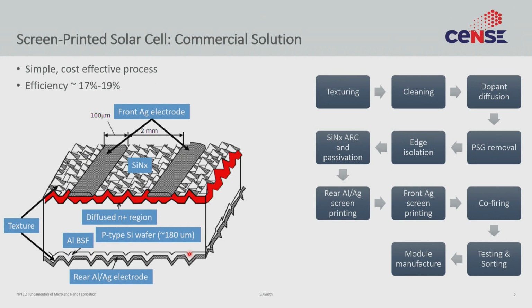Now, why is it everywhere? Because then we don't have to do a lithography step to pattern that, and any saving in lithography is a huge saving in cost. You again see the texturing. We have pyramids. The only difference is we have not inverted pyramids but right-side-up pyramids. As we shall see, this is an easier texture to produce. So even though it's a little less efficient, this is the one that silicon solar cells do. The other thing we notice is the front electrode.